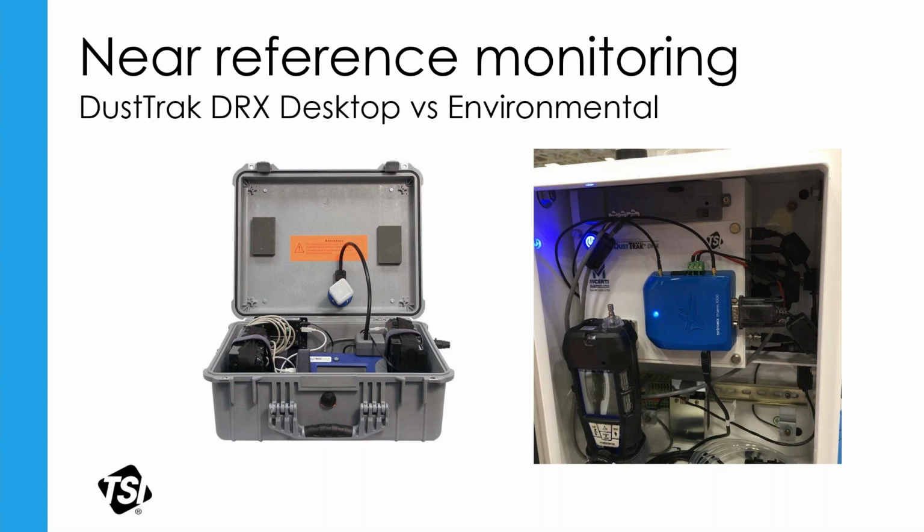So this basically shows you the evolution of how we're changing up our DustTrak that's in the field. And we do have some flexibility as far as powering with it. You can see there in the lower right hand corner in the middle case, we can get batteries in there. Both of these do have the option of a plug and play solar option. So if you are in a remote area and you need continuous monitoring, that solar solution is really nice.